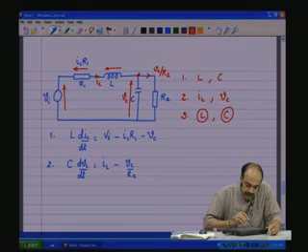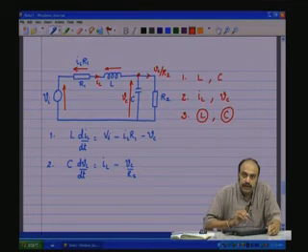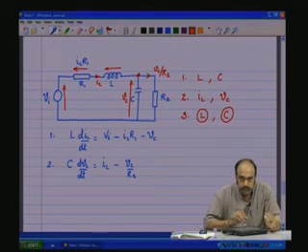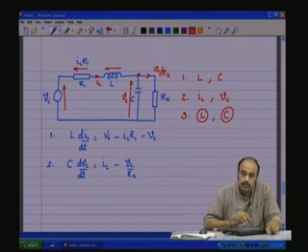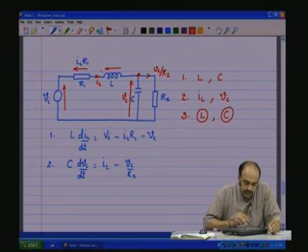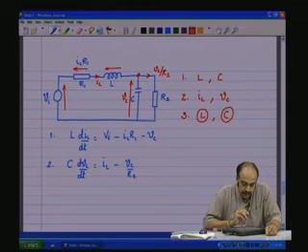As R is in series with L, the state variable IL is used for finding the voltage across R. So, IL R1 is the voltage across that one. So, all the elements, the voltages across them have been identified. Now, apply KVL for this loop. You will get one dynamic equation corresponding to that particular energy storing element.